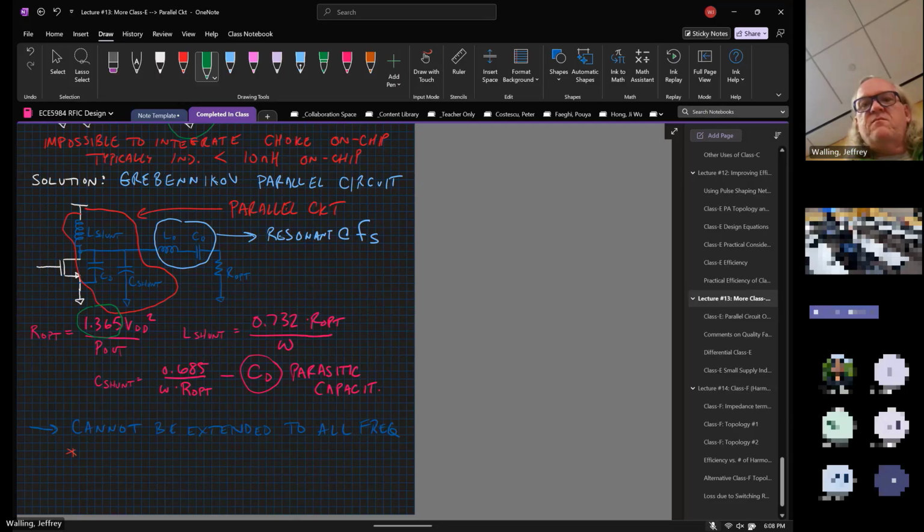Why is it bigger? Because I don't have to make as big an impedance transformation to get down to that value. So my matching network losses will be smaller, and I also don't have as severe a division between the transistor and the load termination.